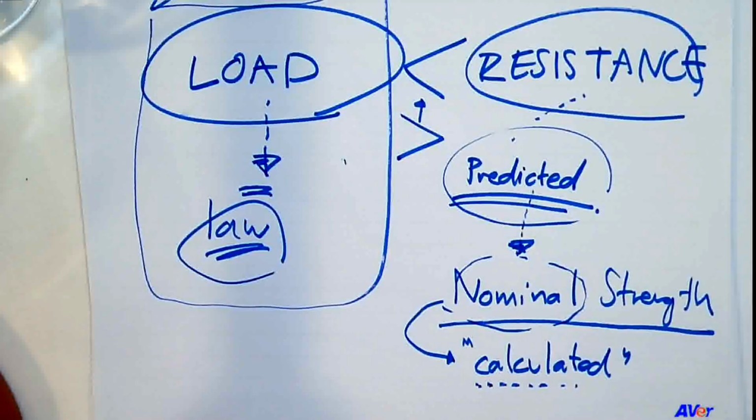Let's say we have like 40 people here and perhaps this room is designed to withstand a live load, maybe 400, because it is a public place, but this is not 400. And even so 400, maybe can we have the load exceed 400 one day? Perhaps, right? Let's say there's a flood event and this turns out to be a shelter for people. So people just bring the stuff in, the logistics and the rice and food and so on, they just pack in this room. So there's a chance that the live load may exceed 400 as well. That is the uncertainty of the load.